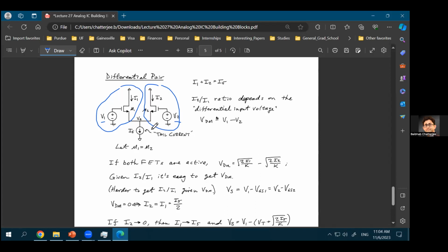And again, why is that? All of you know about the superposition theorem, and there was a question on superposition theorem in your exam number 1, right? So if we apply superposition theorem here, we analyze this by having only the V1 voltage source first, and the V2 voltage source does not exist. Let's just assume it for a second.